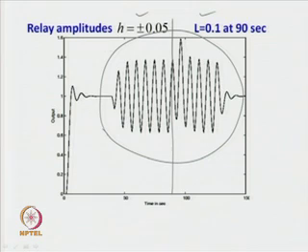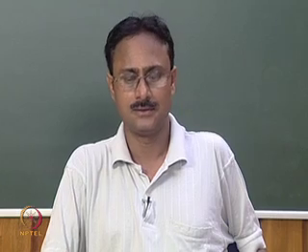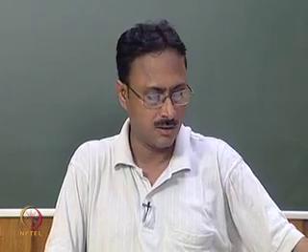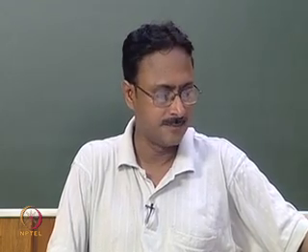So, it has become a bit higher as we look at the output signal, the excursion around the steady state value is very high. Just for the sake of illustration, we have chosen the relay amplitude of high value, otherwise one can choose a small value and get the limit cycle output of desired magnitudes or of desired heights.